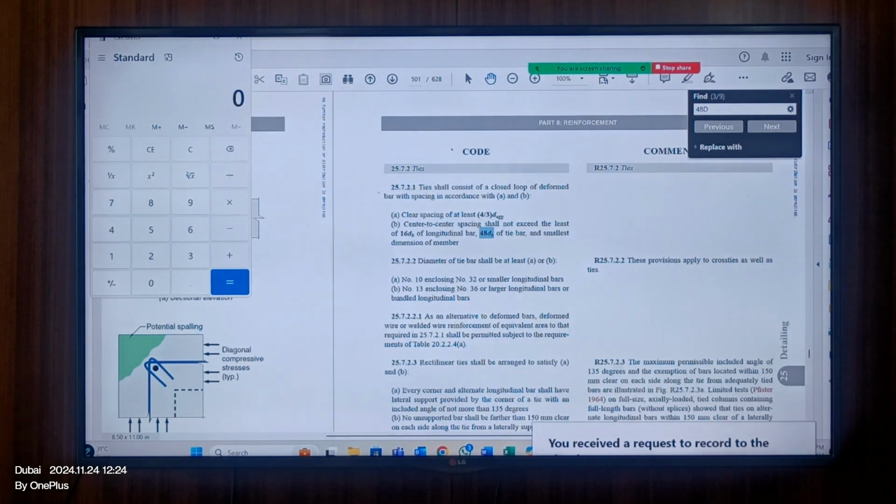So this is the height up to which you have to add shear ties: LD, only the development length. If my LD is 2 meters, this is what I'm telling you. Might be your shear wall width is 400 millimeters, then I'll follow 400 millimeters, only 4 bars. Might be your tie spacing for such a shear wall is maybe 125 millimeter spacing, 12 millimeter. You can use the same diameter as this, but you don't need to follow the same spacing above the LD.